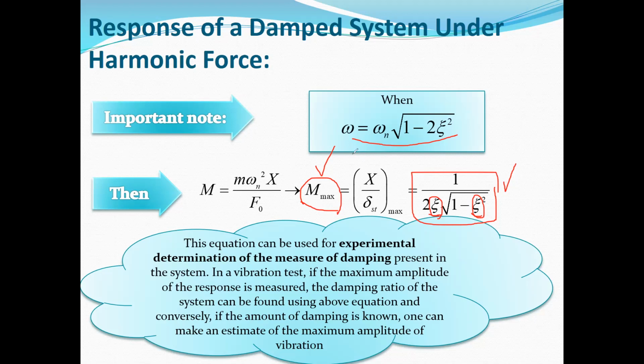For example, if you want to control the vibration of a building, you need to know the equivalent damping for this structure. You can find this psi, and using it, you can consider an equivalent viscous damping in your system and then extract the equation of motion. When you have the equation of motion, you can do your analysis such as control, and, for example, optimize your motion, your vibration and other parameters.